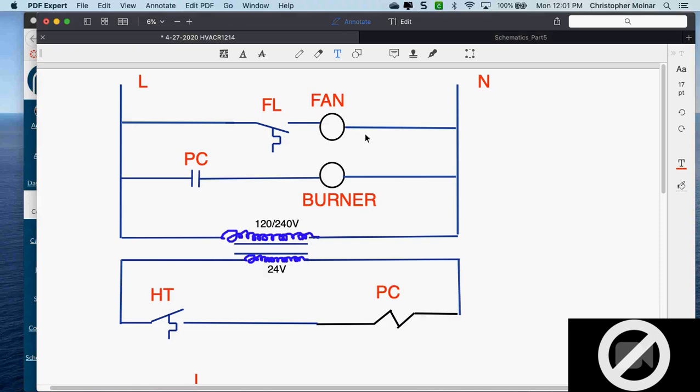That clears it up for me, because I was going to ask the same thing. I know somebody sent me an email on it too, and I forget who. But basically, electric takes the path of least resistance. Now, the thing to be very careful about is which leg of the circuit you're taking that bypass to. Is it going to be line or neutral? And don't give the answer on the call. Just think about the sequencing. Got it. Thank you.